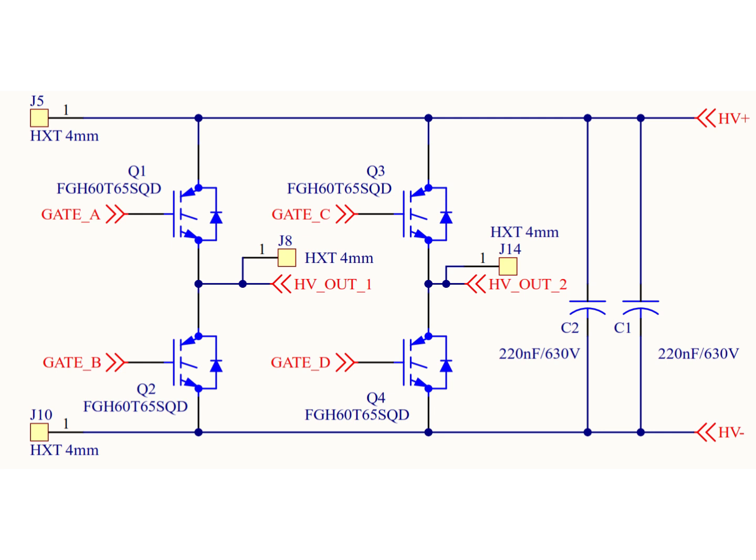In a single-phase H-bridge, each IGBT conducts for roughly half the cycle, so the average current per device is in the 7 to 10 amp RMS range, with peak currents around 20 amps for a sinusoidal waveform. This means the devices are operating well below their thermal current limits, giving us 2 to 3 times headroom, even under continuous full-load operation or mild overloads, a key factor for long-term reliability.